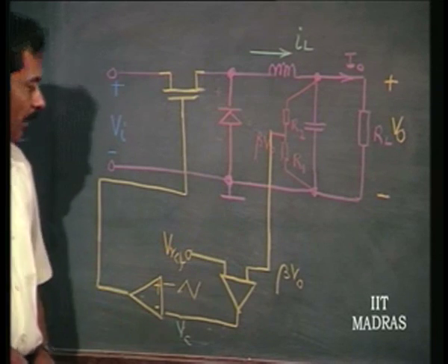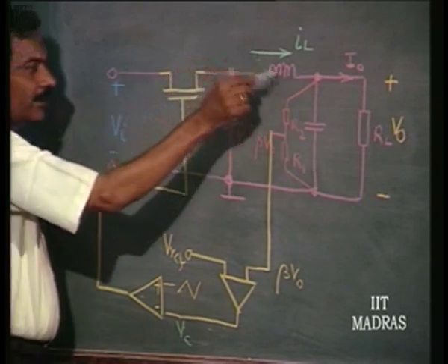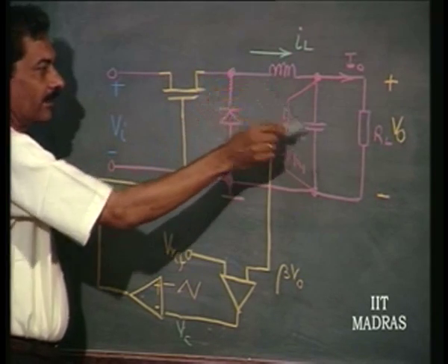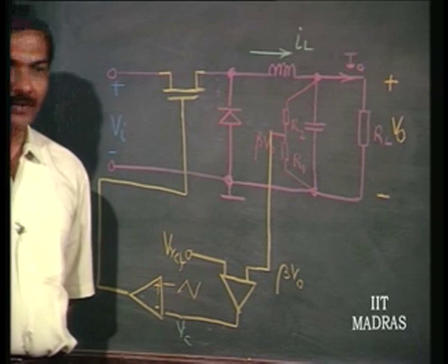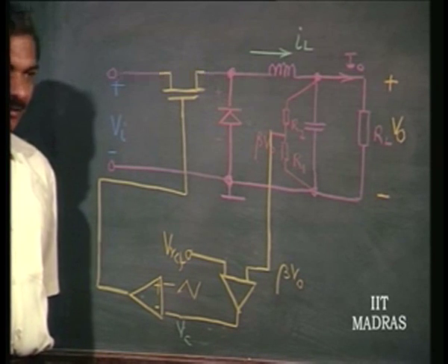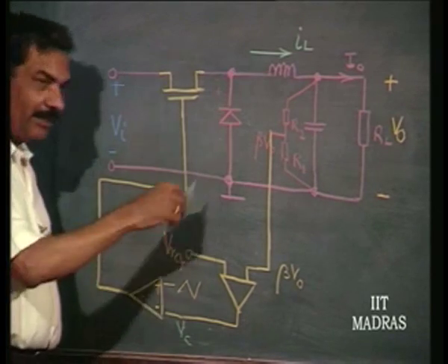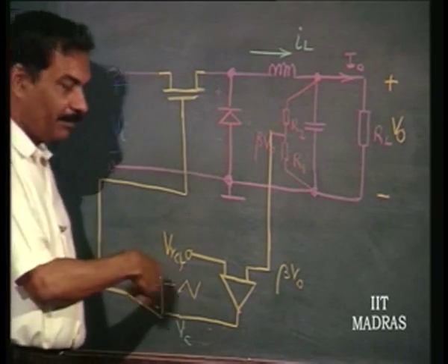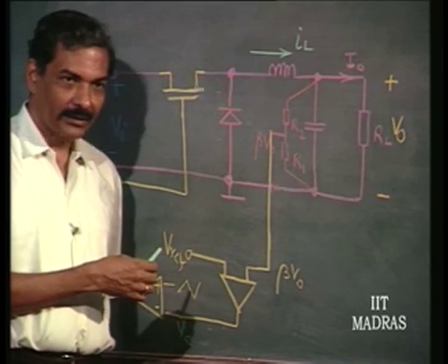So, this is quite popular, and therefore, you see most of these circuits, L, C, diode, and even the switch might have to be provided externally, because these are going to be power components. The rest of the components, control circuitry and the pulse generator and all these things can be put internally.